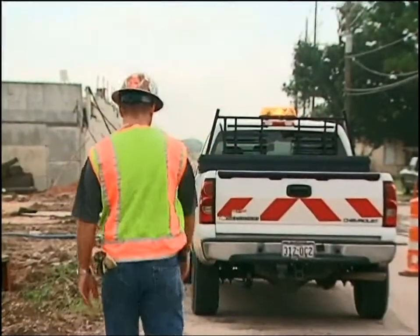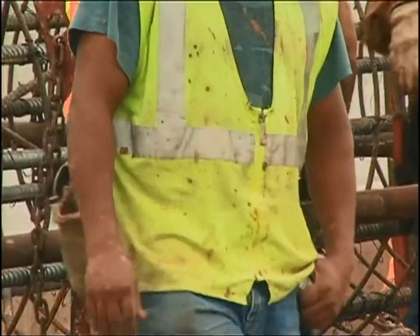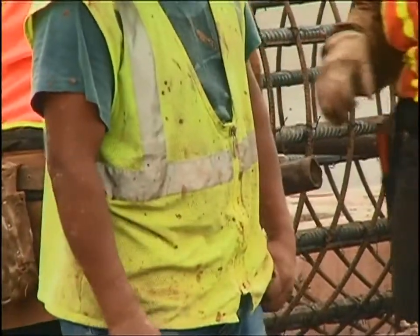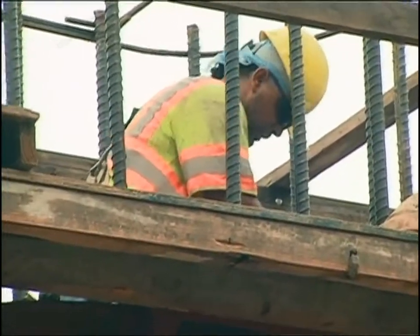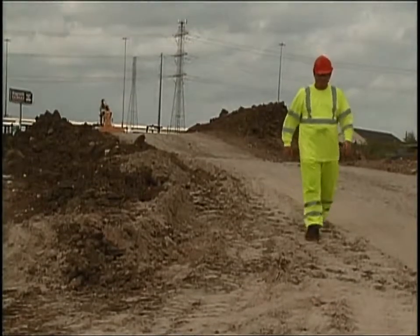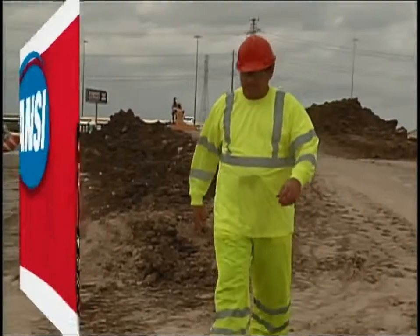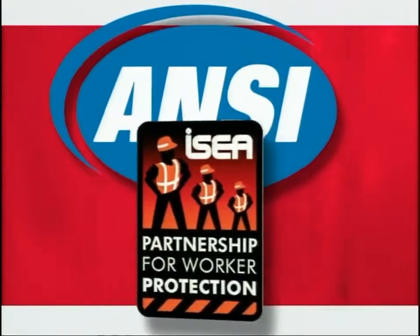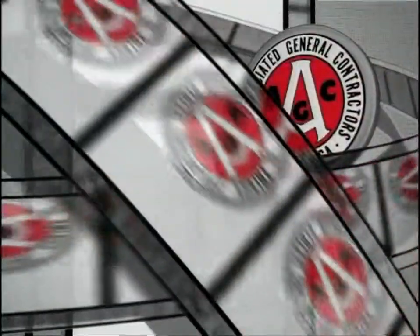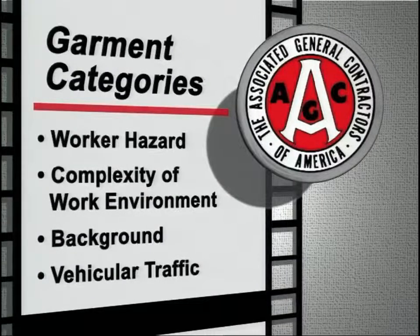When working in road construction zones, always wear high visibility safety apparel with or made of reflectorized or high visibility material so that you can be seen by other drivers or heavy equipment operators. This apparel includes high visibility headwear, vests, jackets, coveralls, trousers, and harnesses. The American National Standards Institute and International Safety Equipment Association define three garment categories which are based on worker hazards and tasks, complexity of the work environment, background, and vehicular traffic.